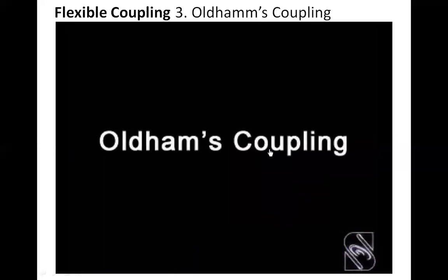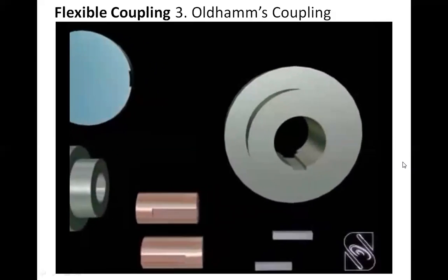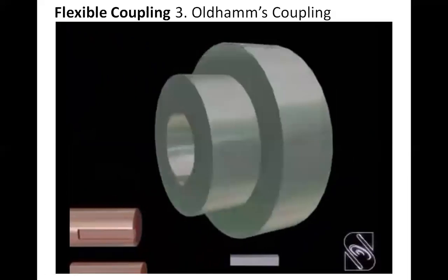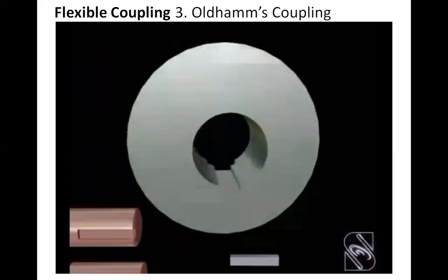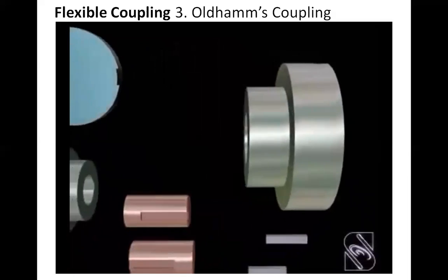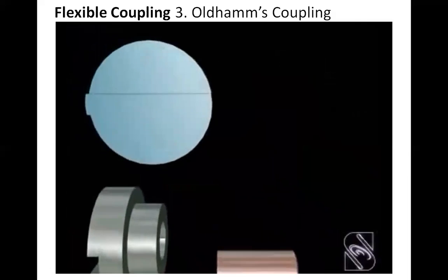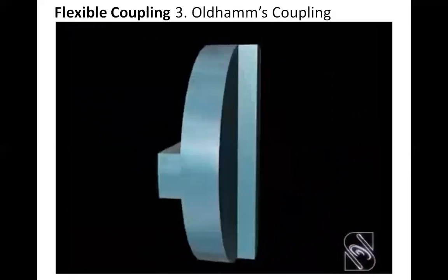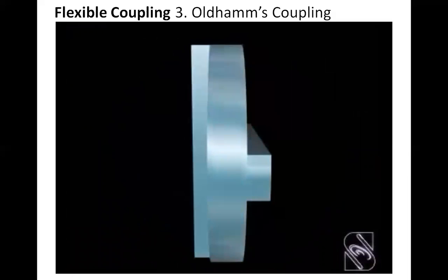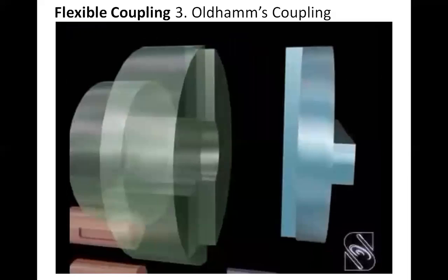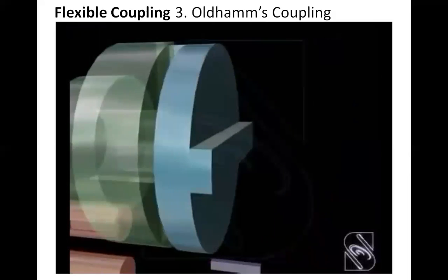The next is the Oldham coupling, which is also not in our syllabus for design purposes, but we must know what an Oldham coupling is, because many times we have seen this Oldham coupling. In this coupling, the flanges have rectangular grooves on their inner face. The cylindrical center disc has rectangular projections on the side faces running diametrically at 90 degrees to each other.